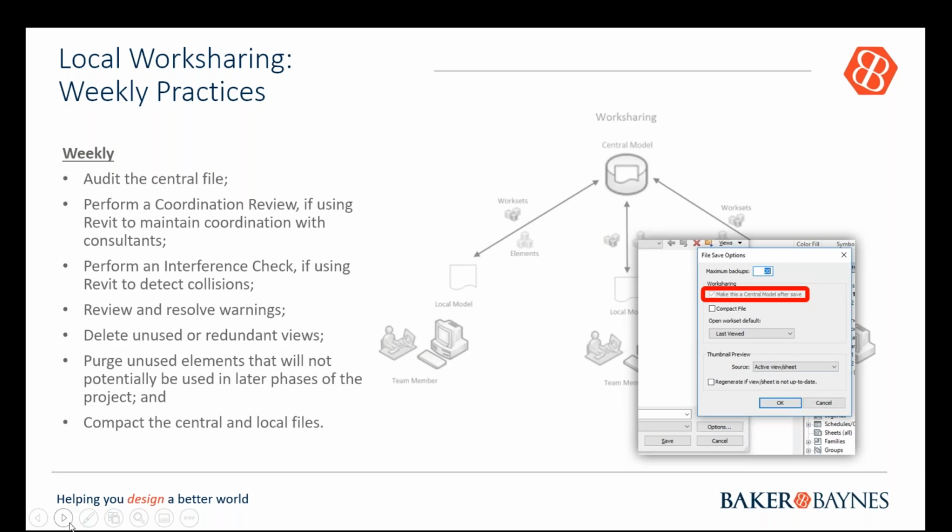So I just clicked and showed you where that is. You want to check those warnings every now and then. Unfortunately, you can't ignore them, so there's no ignore button. You could review them. I've seen instances where there's nothing that you could do about the error, and it just kind of lies there. But there are some where it's duplicate walls or just bad drawing habits. So you maybe want to check those out.